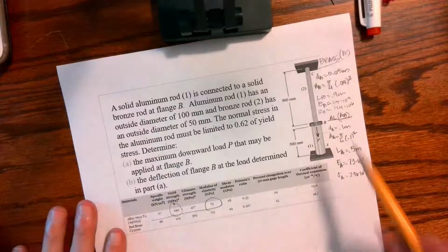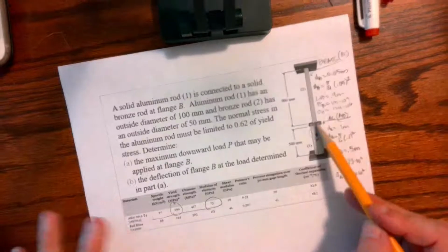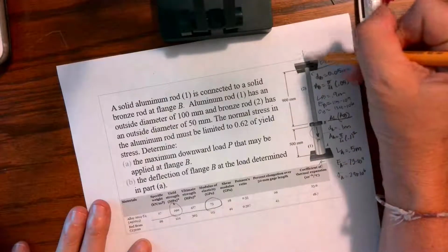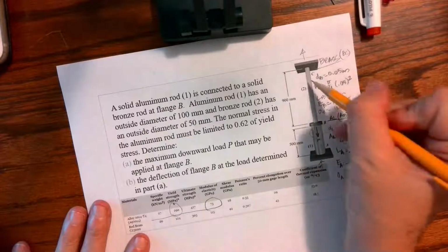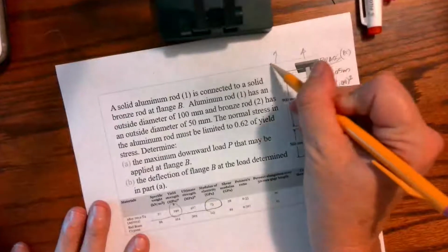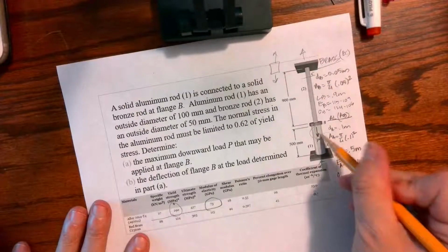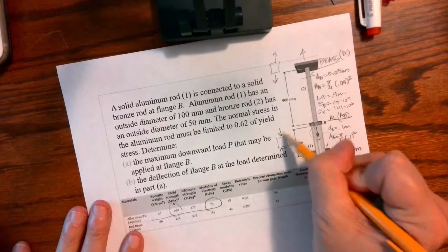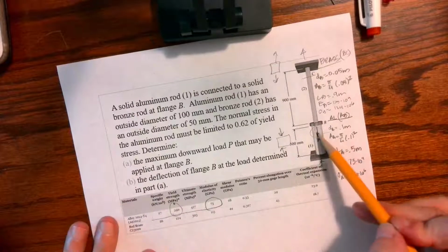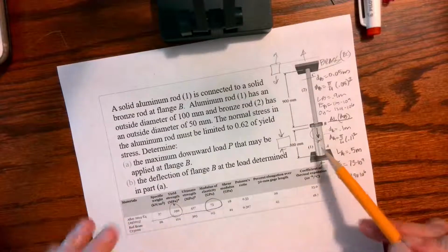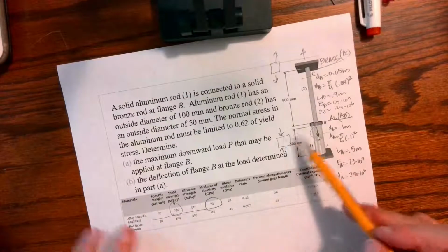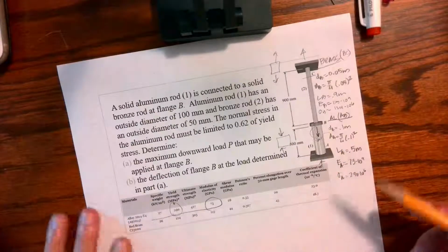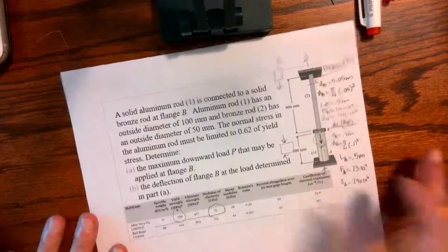So we need to go back and find this P. Well, if I apply a load with this P, I'm going to end up with a reaction at A and a reaction at C. And I know that my internal force is a function of that reaction. And I know if I'm pushing up, that internal is a function of the reaction. And stress is that internal over A, and delta, if we're in the elastic region, is P, that internal, times length over A and E. So I'm going to set everything up just like we did last time.